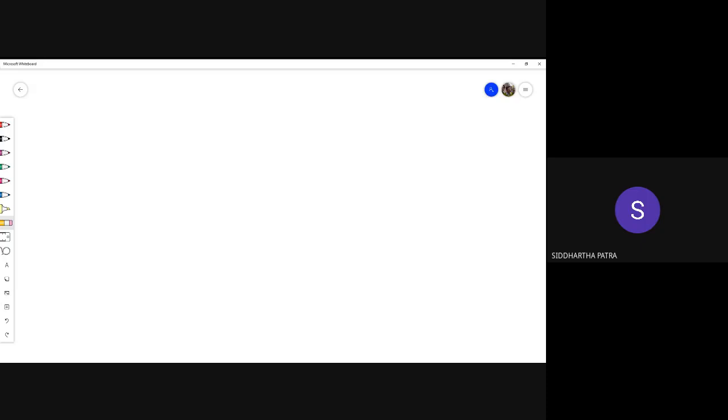In 2D elements, we started with the CST element, which was a three-noded triangle element. In natural coordinates, that was represented with a right angled triangle. But that need not be a right angled triangle. Even though the one on the left automatically became a right angled triangle, in general that is an arbitrarily shaped triangle. So we learned about the CST element, and what we found out is that